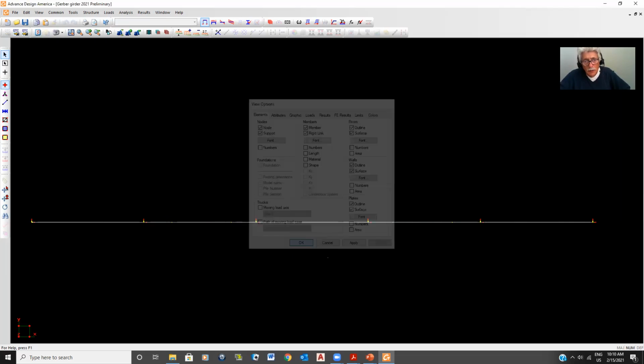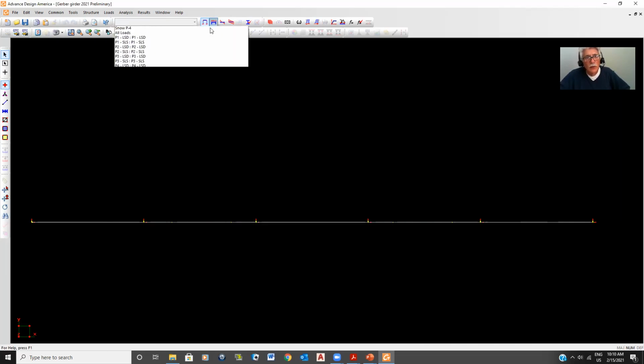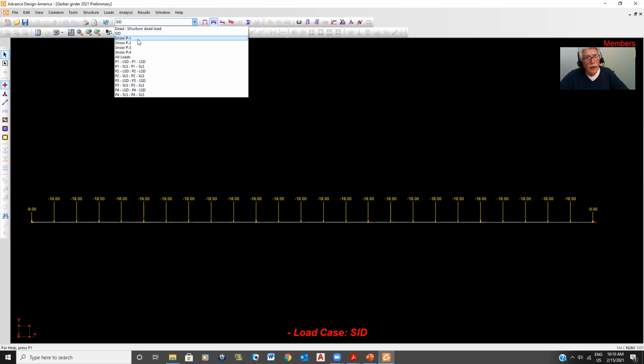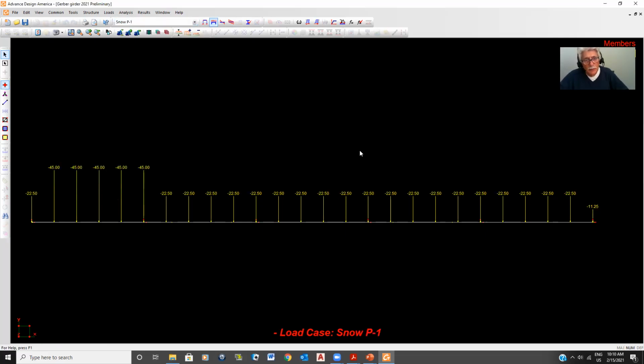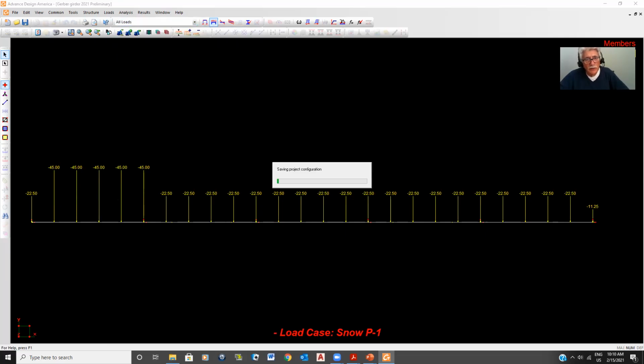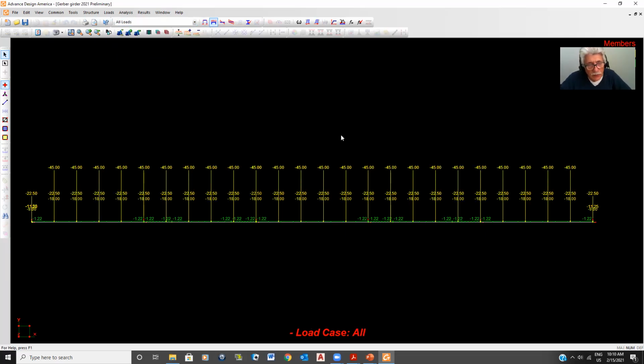Material. Okay. Then of course we had the different load cases. You guys should have your dead load and so on, and then your pattern 1, pattern 2. You should never show these all at the same time because it makes absolutely no sense. You don't even know what you're looking at. This is the self weight of your beam right here, and this is the dead load, and this is your snow load, and you don't know which load case it is. Anyway, these are all your loads.